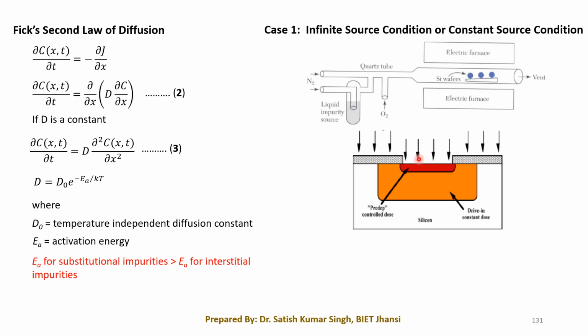Whatever impurities have been absorbed or diffused into this particular layer, you can see by the dashed red line, the red area. Whatever diffused atoms are available in this red zone, when we further heat the wafers after shutting off the supply of impurity atoms, these atoms are going to further diffuse into your wafer. Only this amount of atoms. There will be no supply of impurity atoms afterwards.